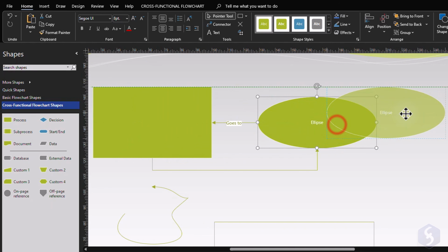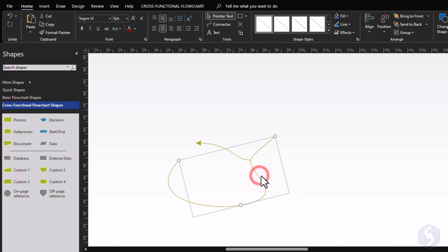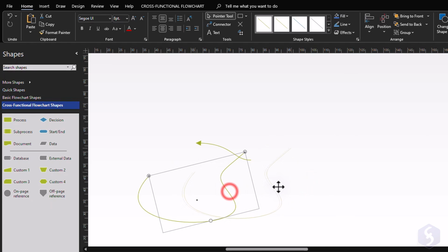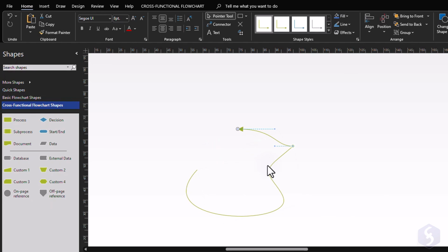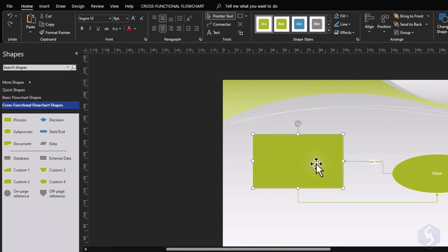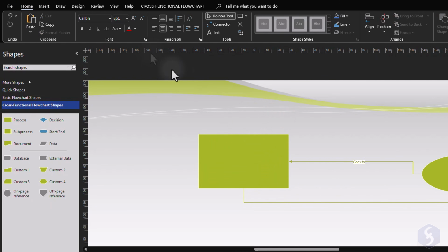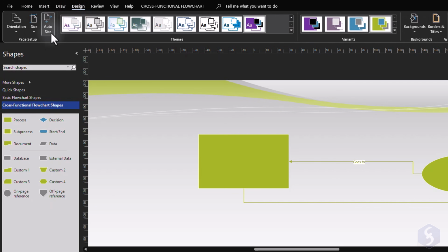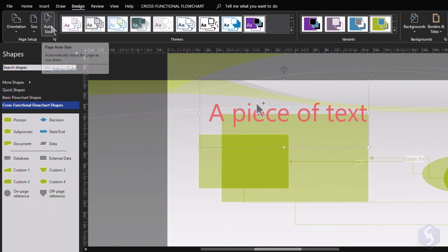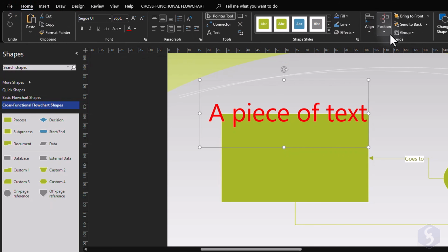When you move any shape with connectors, these too get updated. If these do not follow the shape, make sure that the wires are attached to any connection point first. If you move any object outside the page borders, this gets extended if the Auto Size option is enabled under the Design tab. If you get objects overlapped, you can adjust their order of visibility with Home Arrange.